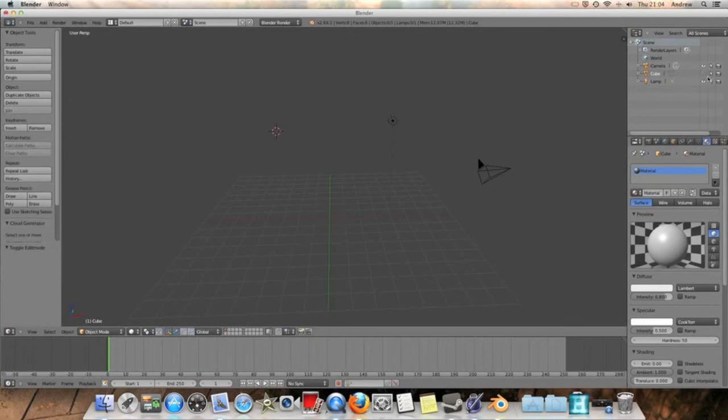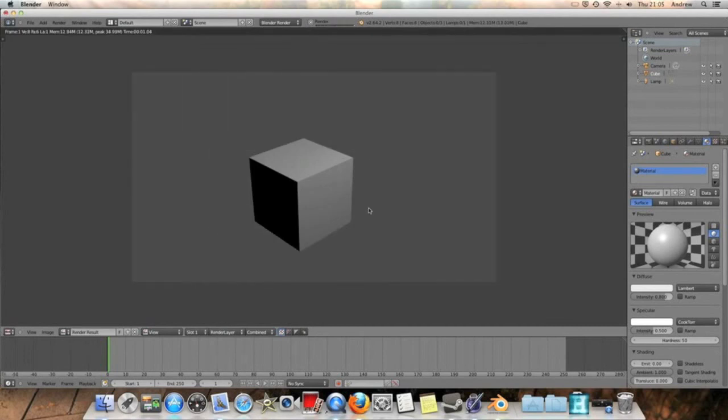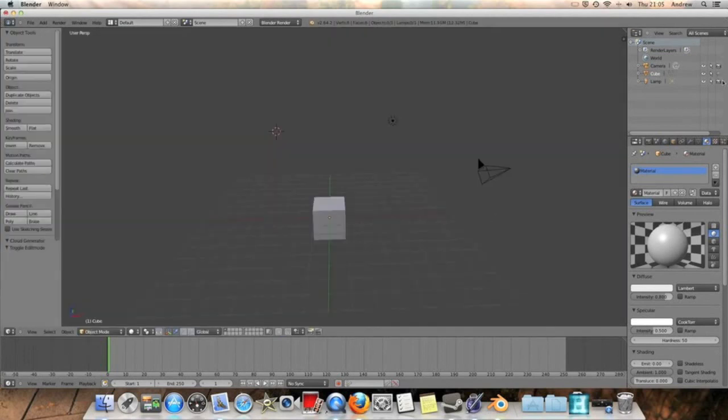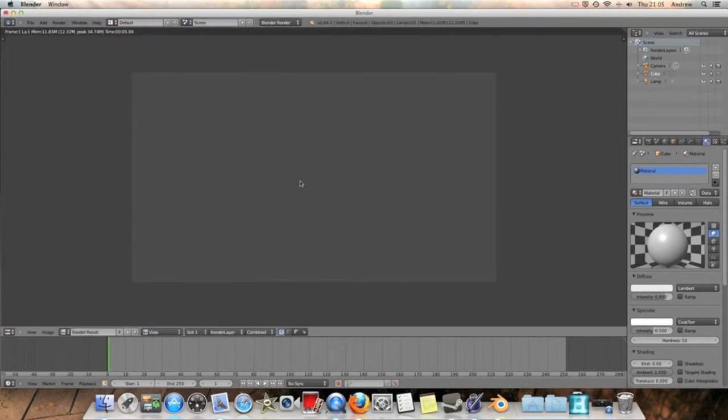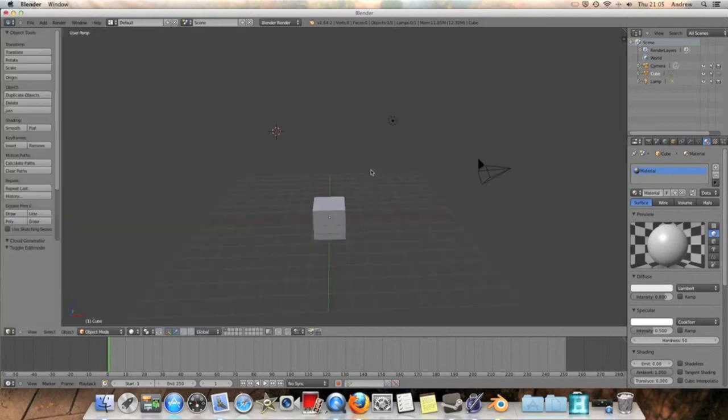So from sight, if you want to close the eye to make it invisible, we'll ignore the mouse, that doesn't do much, locks it really. And then also the camera here, if we uncheck that, that means that it's invisible from the render. So if I render an image, we can see the cube. If I take away the camera, we can render an image again, and we've taken away the cube. There's no cube in the camera's view, according to the render.